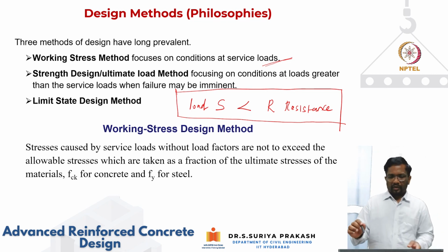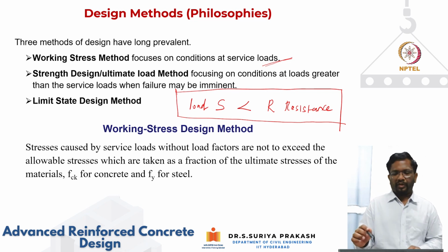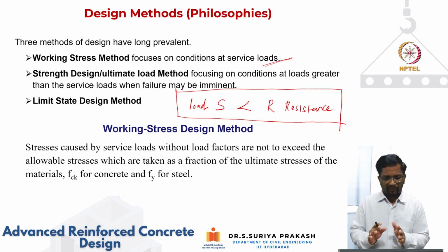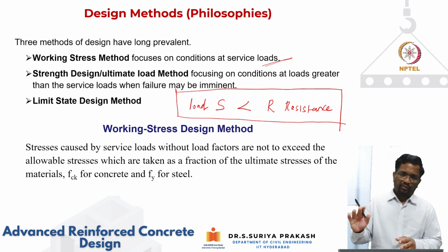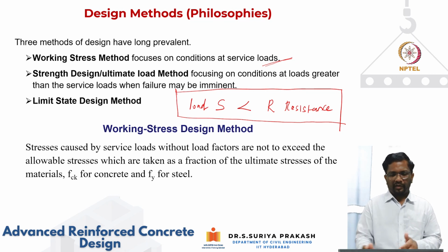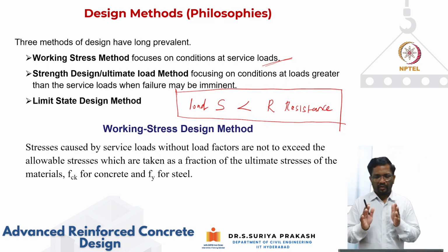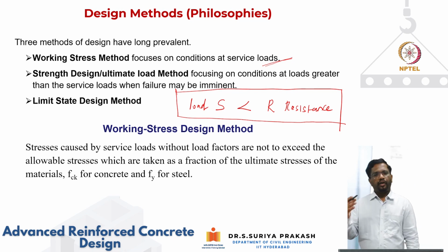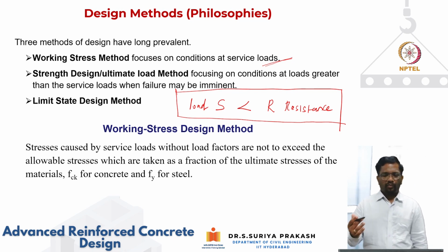Now in the working stress method, we look at the service loads. We do the analysis for service loads, and we don't use any load factor. That means I'm not going to amplify the load effects by any factor. I'm just going to take the internal forces for the service load condition. But I will make sure that those load effects are less than the allowable stresses. And what are allowable stresses?